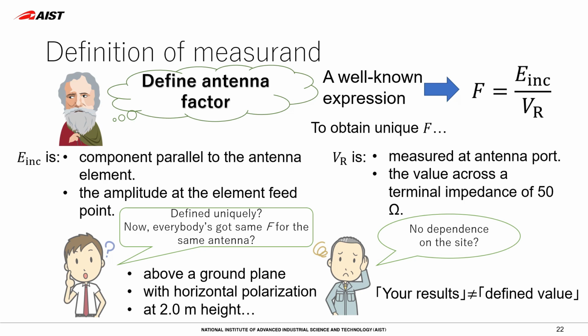Have we defined the antenna factor uniquely now? Not really. Antenna may be used at an open test site, maybe with horizontal polarization, maybe at a specific height such as 2.0 meters. And different measurement site may give you different results.